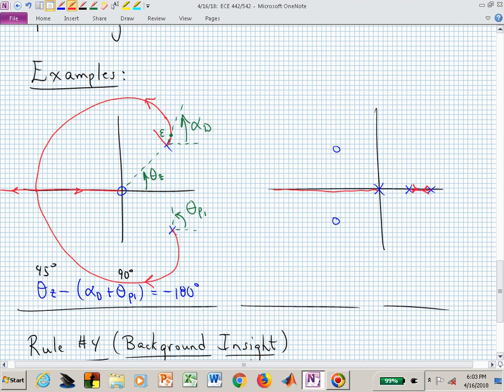They are breaking away, and you could calculate the breakaway between those poles by calculating the relative max of k between those values of z. Then what happens? Well, then they leave and arrive at those zeros.